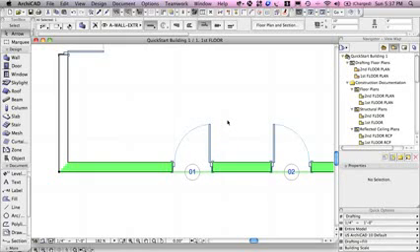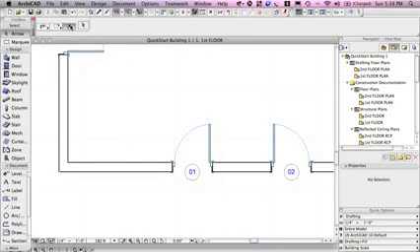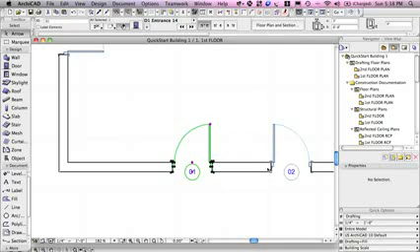It's just one of the odd interface things about ArchiCAD that Graphisoft decided that when you do an area selection, you will select independent elements, but doors and windows are parts of a wall, and so they won't put handles on these. In order to select a door or window, you need to select by arrow clicking on a door on one of its handle points or grips, like this, or if we have the quick select active, then I can go in the middle of this area here to select it. But I can't do an area selection to select doors.